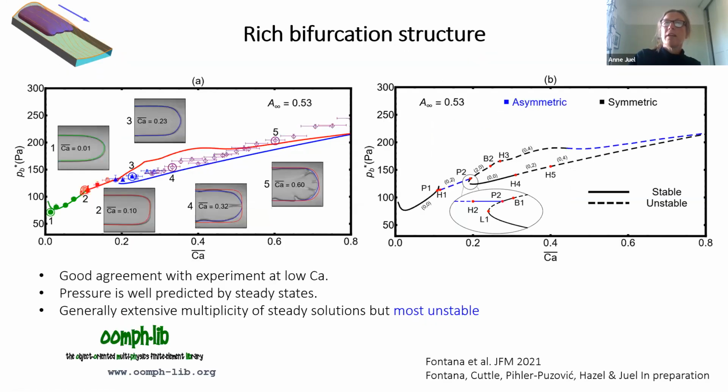But what we also do in those simulations, for the ones I showed here, is that this agreement is not easy to get. If you just coupled the Föppl-von Kármán to a lubrication model, you wouldn't get anywhere as good an agreement. What really is underlying this is that we also have to take into account the thin film of liquid that's left behind the finger as it advances. The liquid is wetting the channel, and it leaves thin films on the top and bottom.